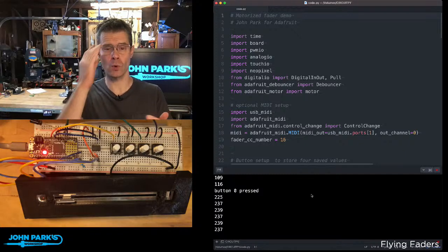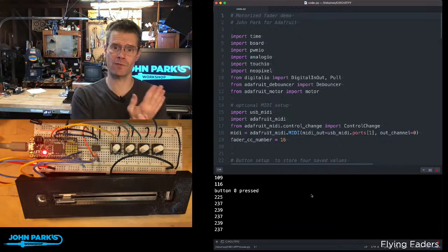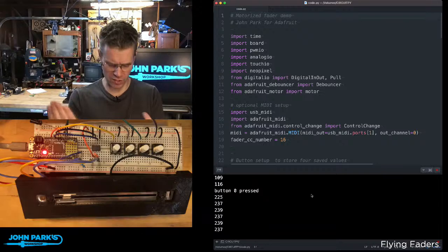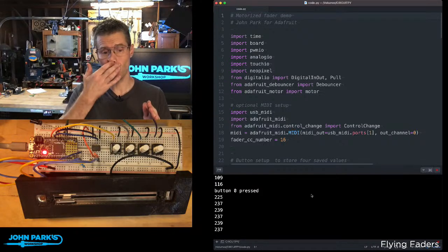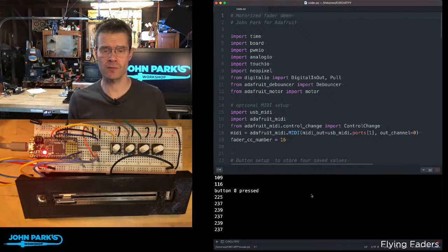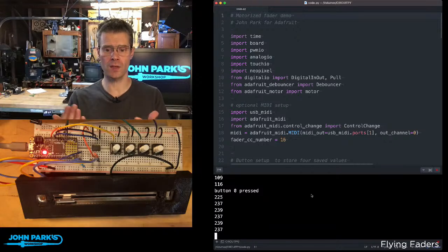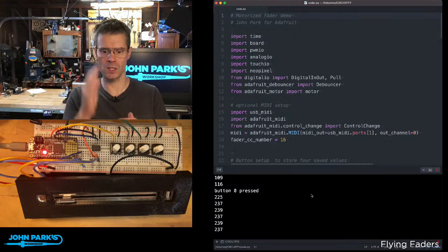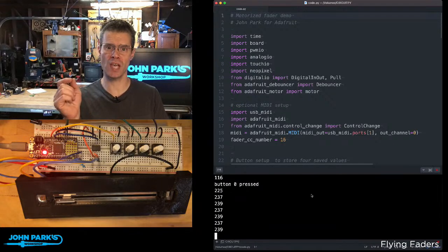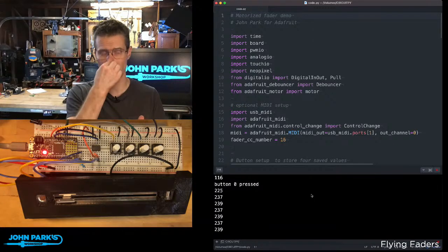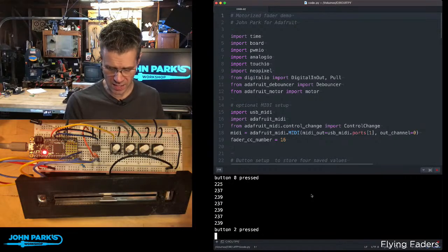Issues you can run into, of course, are overshoot. It can go past if the timing isn't right, and I've seen that happen. Sometimes it'll jiggle a little. Happens worse if you're traveling really fast, let's say all the way from one end to another. Also, if you find that it's overshooting, what you can do is have the speed with which it's moving reduce as you get closer and closer to the target, and that's why you'll see I have this nice ease to it.